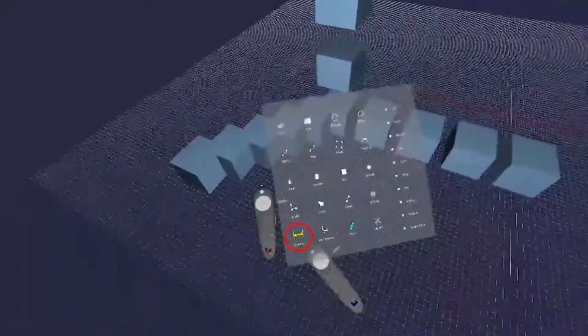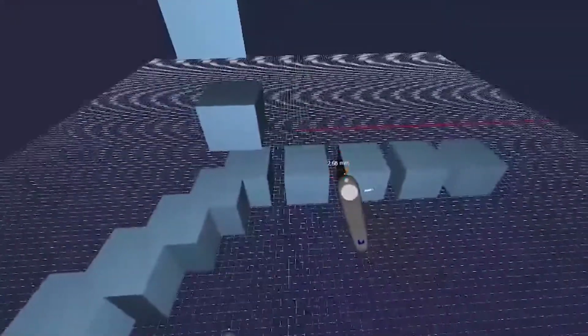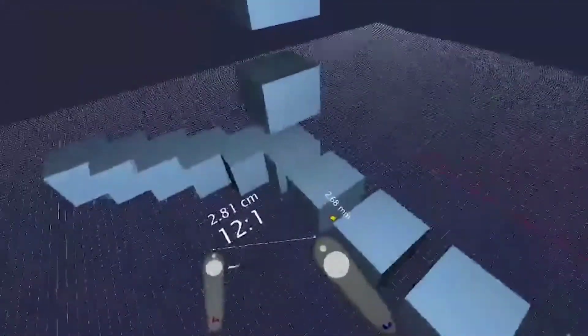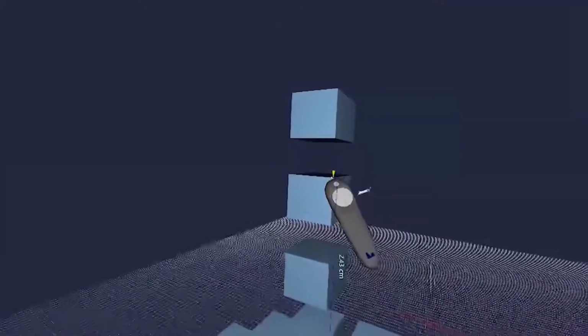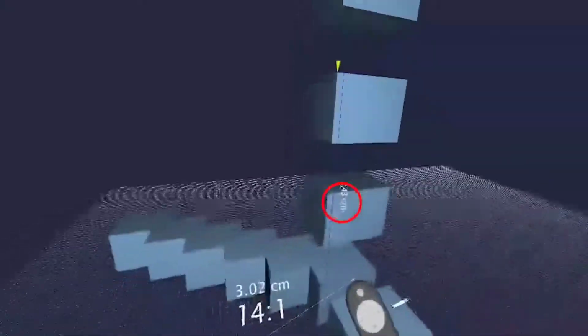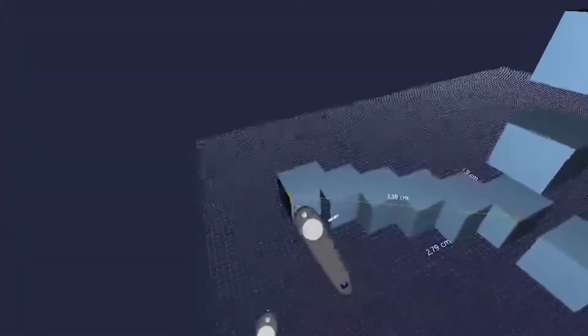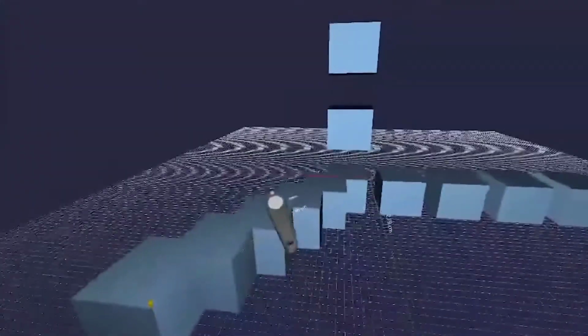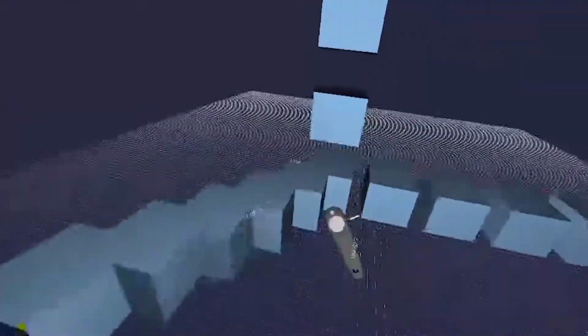And now using the dimension tool, I can confirm the size in between and the spacing. I'll make sure my end snaps are on so I can grab the corners, and boom, you can see the dimension show up immediately. And it stays there for you to reference. I can also do this in the vertical direction between 2 pieces. And again, you'll see that in the vertical. Additionally, you can dimension diagonally, and in this case you're going to get 3 dimensions that show up. The X, the Y, and of course the diagonal that you are looking for.